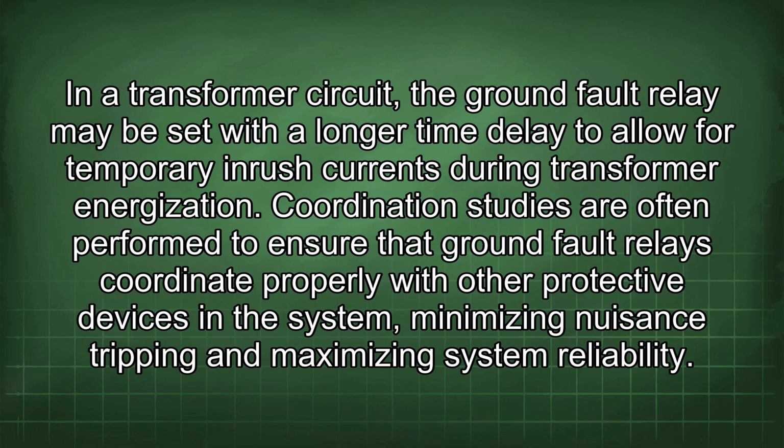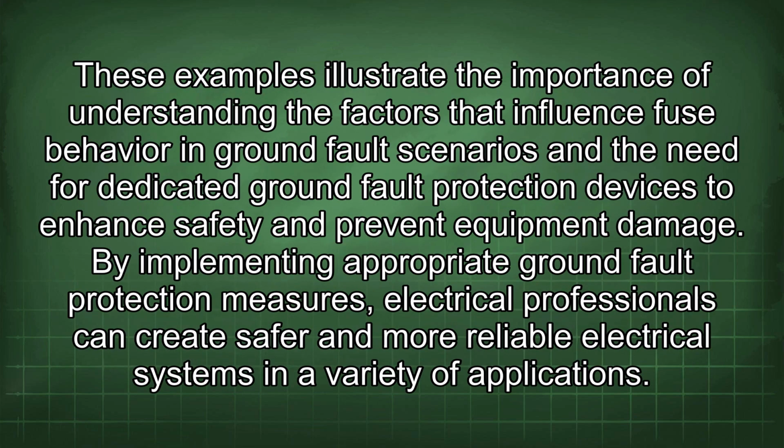In a transformer circuit, the ground fault relay may be set with a longer time delay to allow for temporary inrush currents during transformer energization. Coordination studies are often performed to ensure that ground fault relays coordinate properly with other protective devices in the system, minimizing nuisance tripping and maximizing system reliability. These examples illustrate the importance of understanding the factors that influence fuse behavior in ground fault scenarios and the need for dedicated ground fault protection devices to enhance safety and prevent equipment damage. By implementing appropriate ground fault protection measures, electrical professionals can create safer and more reliable electrical systems in a variety